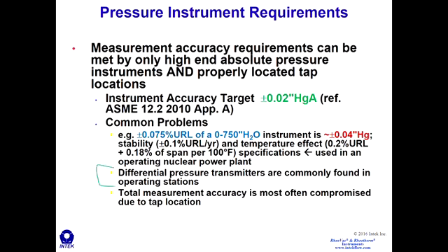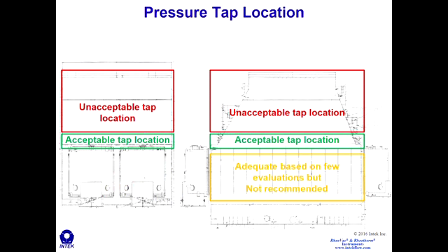We often see differential pressure transmitters used in operating stations as well, so just going up and looking up the model number and checking that out can be a valuable exercise. Just to reiterate that specification, the measurement needs to be made 1 to 3 feet above the bundle. Here's just a pictorial example.